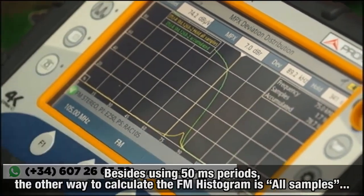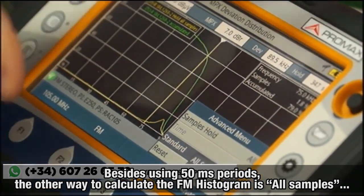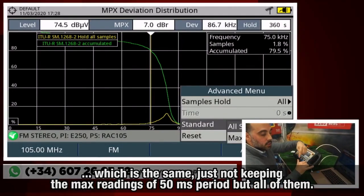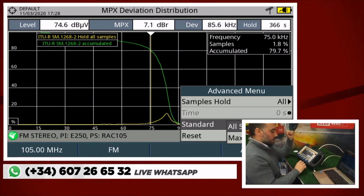Now, I told you that there were two ways of calculating this. The other way, all samples, the meaning of everything I explained is exactly the same. The only difference is that when I'm taking all those measurements over the MPX FM deviation, I don't just keep the maximum reading of every 50 milliseconds period, but I keep all of them, and I use all of them to plot these graphs and to calculate these numbers.